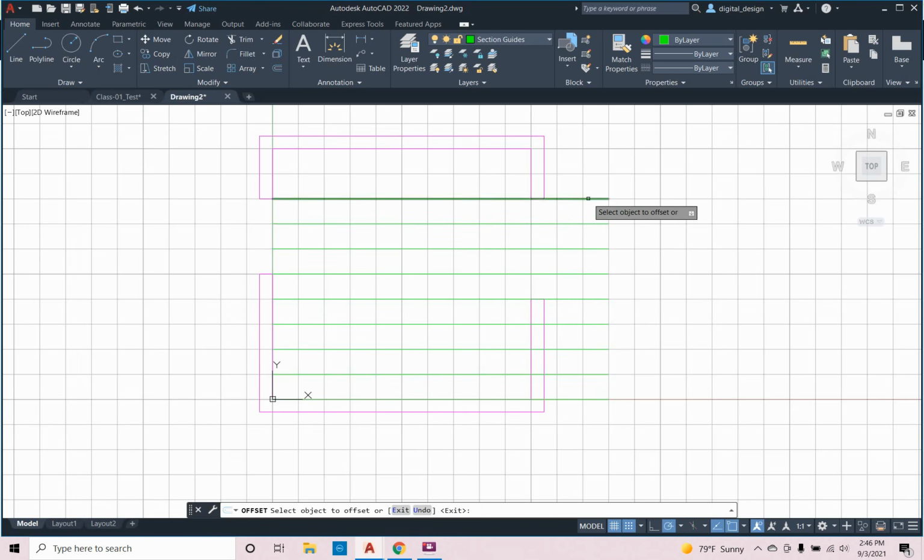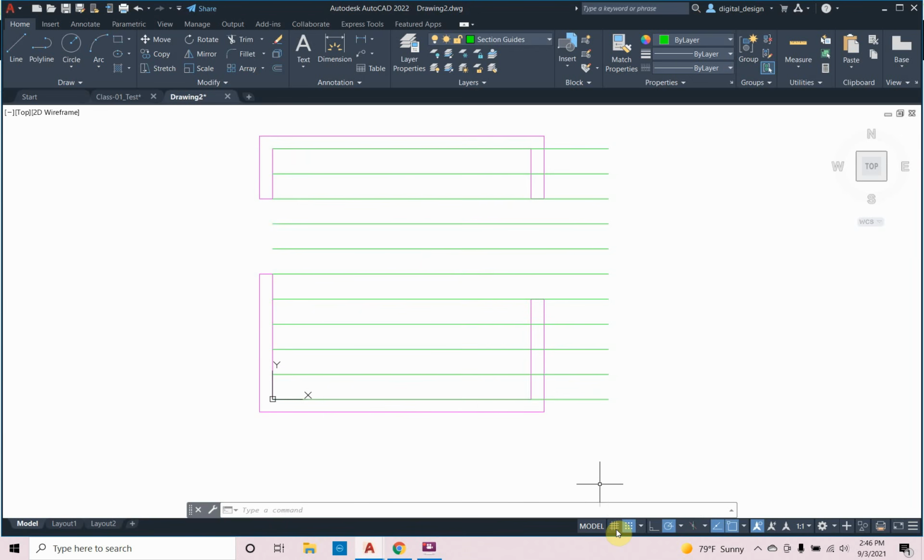Okay, so what's one reason to do this that I'm doing right now? One reason is you'll need to know where the sections are going to be cut, so you know which furniture they're being cut through. Let me turn off the grid for a second. At the bottom of the screen, I have my grid mode, so I can turn that off. Now I'm going to be taking 11 sections. So I'll have 11 vertical sections through this bedroom, and I'll also know where they're being taken.